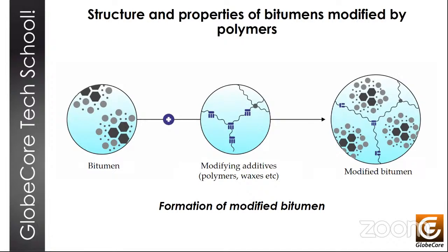So if you look at the properties of polymer bitumen compositions with 3 to 5% polymer content, you will find a noticeable increase in the brittleness point without increasing the deformability of bitumen. It's obvious that a decrease in the brittle point occurs due to an increase in strength. At a higher concentration of polymer in bitumen, the compositions can be considered fibrous or layered.